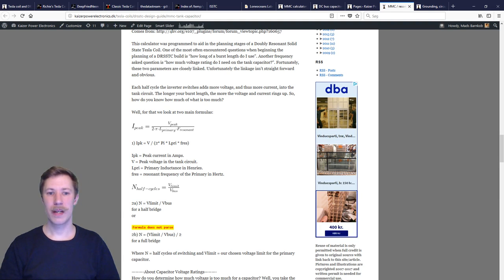So this really only gets interesting when you're doing a low impedance coil, where you want to look into how fast you can achieve your peak current. My approach is at most that I just look at, okay, if I have to switch for 250 microseconds, well, I do that. Whereas some people look into, okay, I want to switch below 100 microseconds and still achieve the same current.